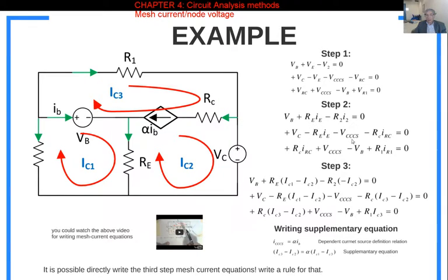And what is left here is this element voltage. What is this element? That means current controlled current source. So while we are writing the Kirchhoff voltage law equations, we met the voltage of this element in mesh 3 and in mesh 2, in two places like that. So this element definition relation is here. If you look at this definition relation, this element voltage is not seen. So I cannot replace this voltage with the current of this element by using the definition relation. So I am going to keep this voltage as it is.